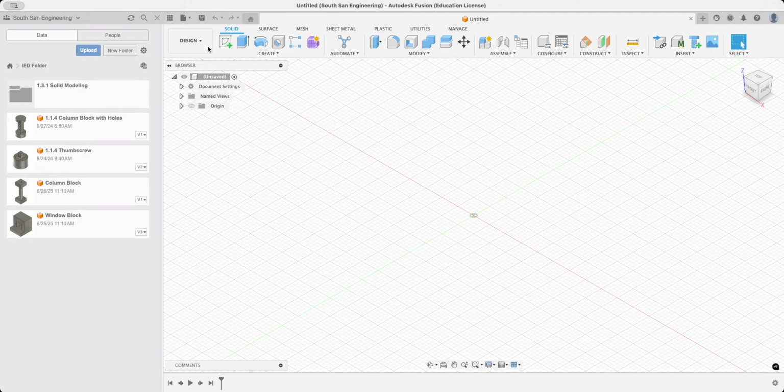Well, three things. First, under general, scroll down where it says default modeling orientation, and change this to Z up if it's not already Z up. All our machines, our additive machines and subtractive machines, the CNC, the 3D printer, all those work on Z up modeling. Then we're going to go down to default units, go to design and change that to inches if it's not, and then go to manufacture and make that inches if it's not. So 3 changes. And then when you're done, click apply and then click OK.